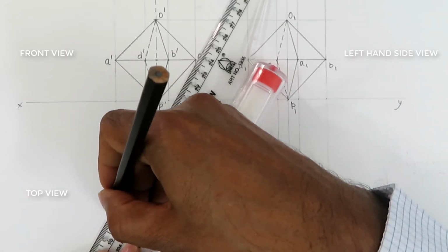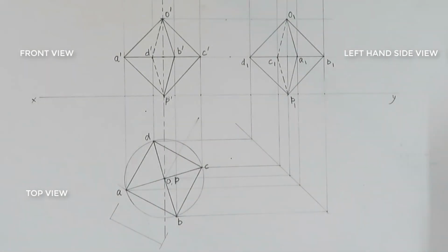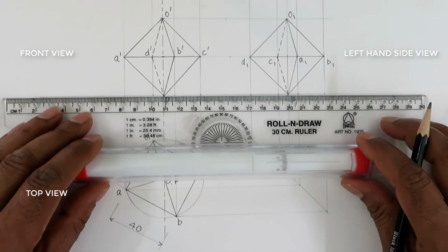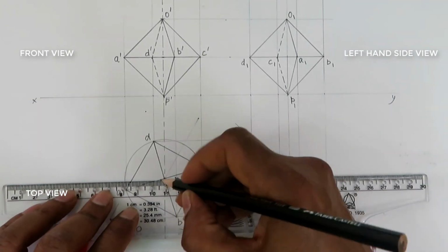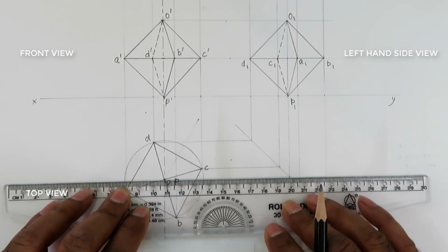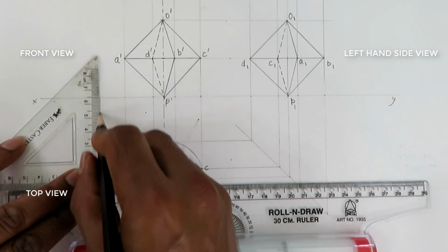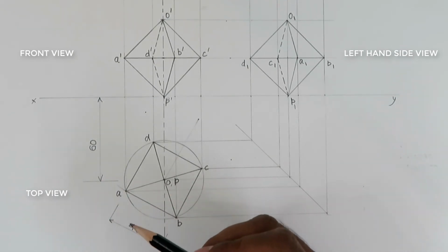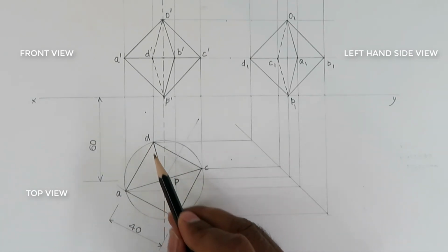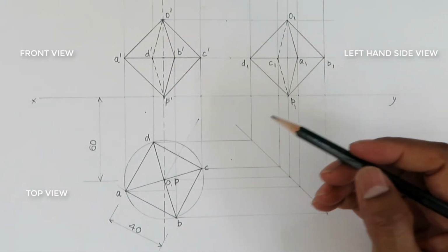So let's do the dimensioning. In dimensioning, we only dimension the lengths which are given. For example, the edge length is given, which is 40 millimeter. Also the location of one of the vertices is given, which is 60 millimeter. So these two dimensions are given, so we will dimension them here. We will not dimension the diagonals because diagonals are not given, these are derived. And similarly the length of the axis is also not given. This is basically the same as the diagonal.